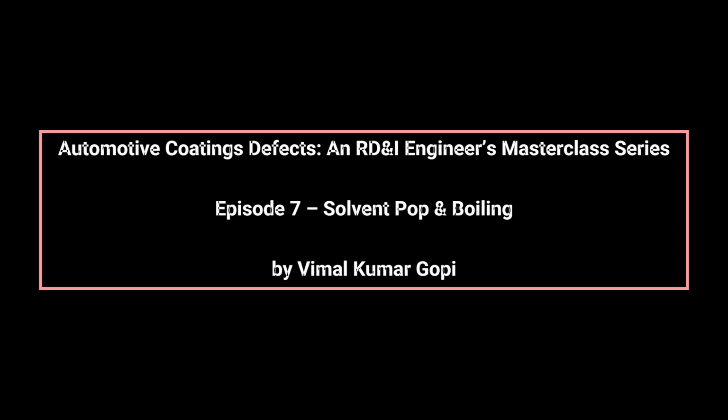Viscosity also influences risk. Low viscosity coatings tend to spray at higher film builds and may encourage over-application. High viscosity systems may trap solvent more easily if atomization is poor, leading to localized thick regions. Therefore, viscosity must be controlled not just for application quality, but for solvent release behavior. Once solvent pop has occurred, there is no chemical fix. The only corrective action is mechanical removal of the damaged film, followed by repainting under corrected process conditions.